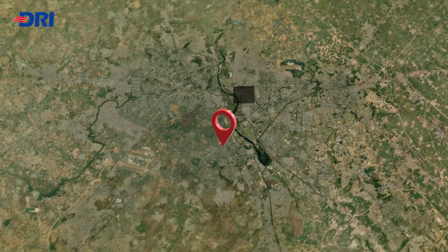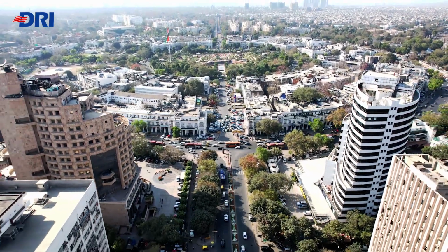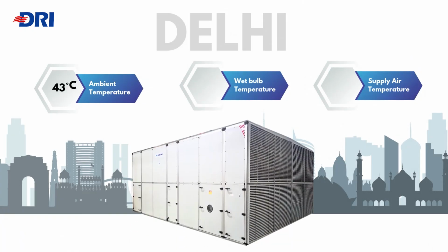In a hot and dry climate like Delhi, where summer temperatures can soar above 43 degrees Celsius, with a wet bulb temperature of around 24 degrees Celsius, traditional air conditioning consumes enormous energy to maintain comfort. However, an IDEC system can reduce the supply air temperature to nearly 20 to 22 degrees Celsius, well below the wet bulb temperature, without relying on high-power refrigeration, significantly cutting energy costs.